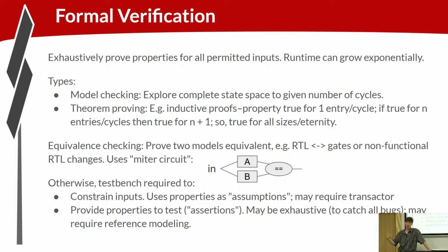But you need to constrain the inputs to legal inputs, whatever the external logic is to the unit under test. There's bound to be assumptions. Maybe this input vector is a one-hot vector. If you're not constraining the formal tools, they're going to come up with a multi-hot vector that violates the properties that you're trying to verify. So you need to define the input constraints as properties.